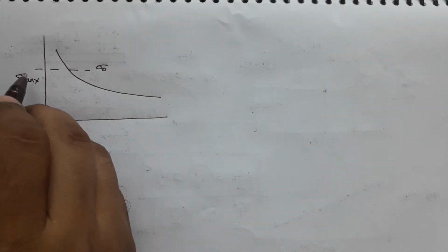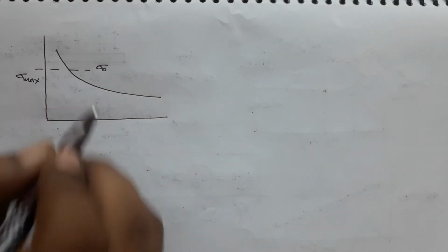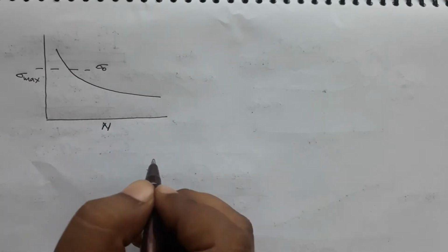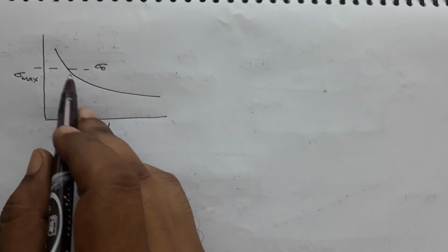So it can be sigma max. It is sigma max because if we plot sigma A, it does not mean we draw a line of yield strength on this plot. This is sigma max versus number of cycles to failure. Even though the stresses are elastic, which is completely reversible, we still have damage in the material.